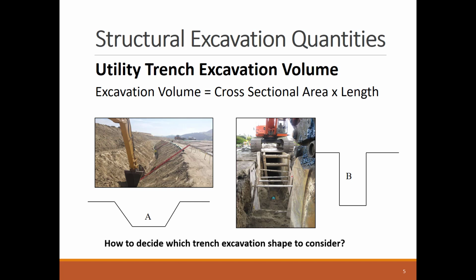When calculating the trench quantities, you will always need to know if you will use a trench box or not. Typically, trenches less than 5 feet deep will not need a trench box per the requirements of the Occupational Safety and Health Administration, OSHA. Depending on the soil type, you can still end up with vertical trench sides without even a trench box, like in the case of rock or clay.